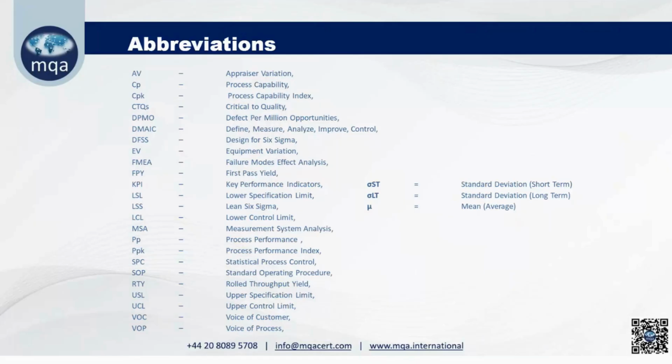And CPK is the index. The index is calculated by upper specification limit minus X double bar divided by 3 sigma, or X double bar minus LSL upon 3 sigma, whichever is minimum. Okay. Thank you.